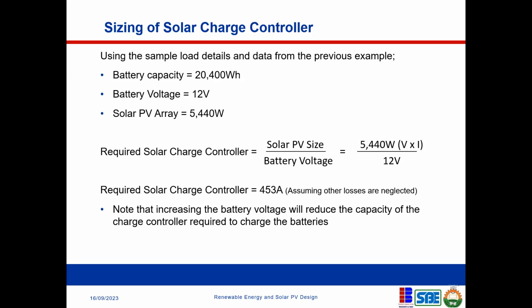So in this case, you will have no choice than to reduce the current rating so that you can have multiple charge controllers connected. And then, like I said, you do different designs, alternative designs. Take the cost and see which one gives you a better cost. So whether you are doing parallel or series connection, as far as I'm concerned, as an electrical engineer, I don't think there is any implication to that. It just depends on what you want to achieve at the end.